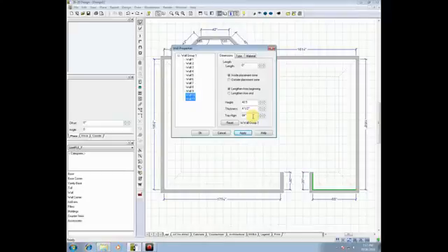So if your default setting in 2020 is 84 inches, but in this kitchen you happen to have used a 42-inch high wall cabinet, you could actually go to the very top of the screen. See where it says Wall Group? I've had you clicking on individual walls and making changes, but if you clicked on Wall Group, you can actually change the entire room at one time.